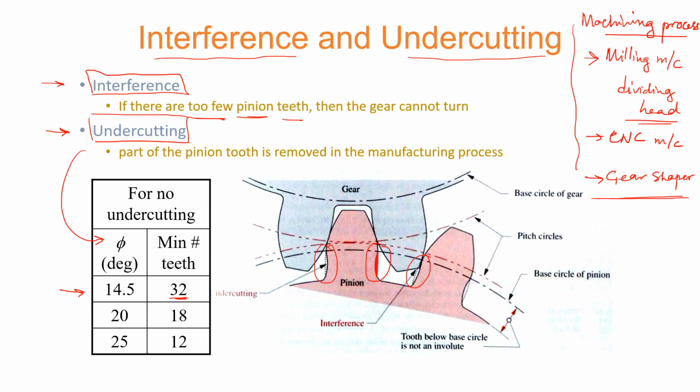Once you have the gears manufactured, what you need to do is improve the surface profile of those. In order to have the surface profile improved after this process, you perform, for example, the grinding operation. There are special purpose grinding machines to grind the gear profiles. Alternatively, there is a shaver machine, or gear shaver machine.